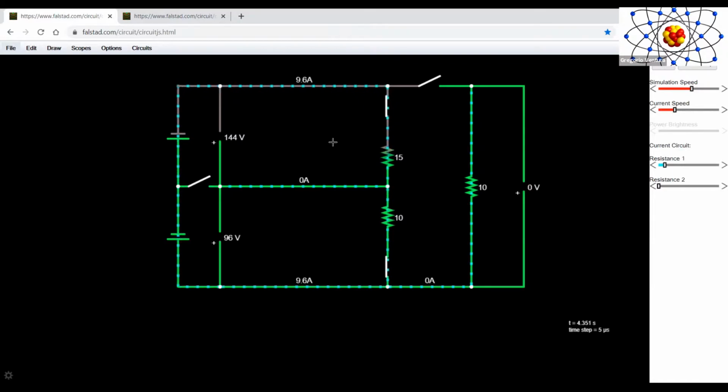Because now these ohms are going to be adding to these ohms, and the total voltage, which is going to be applied between the two loads, is going to be equal to 240. So in this case, our 240 volts divided by 25 ohms is going to give you your 9.6 amps that we have right here on the top and bottom. Under normal conditions, we are going to have 4 amps of unbalanced load, and each device is going to be taking the regular amps, 8 and 12.